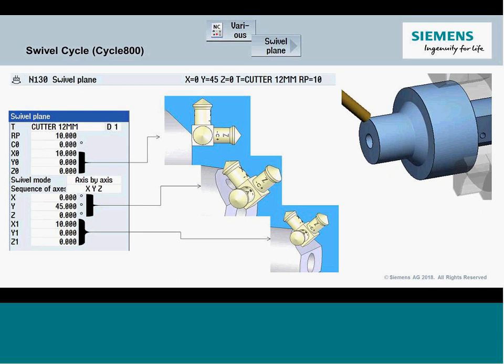The result of that is now your coordinate system is sitting still on that corner of the surface, but now Z is normal to, or perpendicular to, this new inclined plane. Last but not least, and I don't have to do this, but sometimes it makes it easier later, I'm going to stage the zero by sliding the work coordinate system up this newly created plane. So we're going to move up the x-axis in a positive direction, in millimeters. Then if I were to tell a tool to go 0, 0, 0 for x, y, z, it should be touching the center point of that plane. That's my new zero at the time of this swivel function.